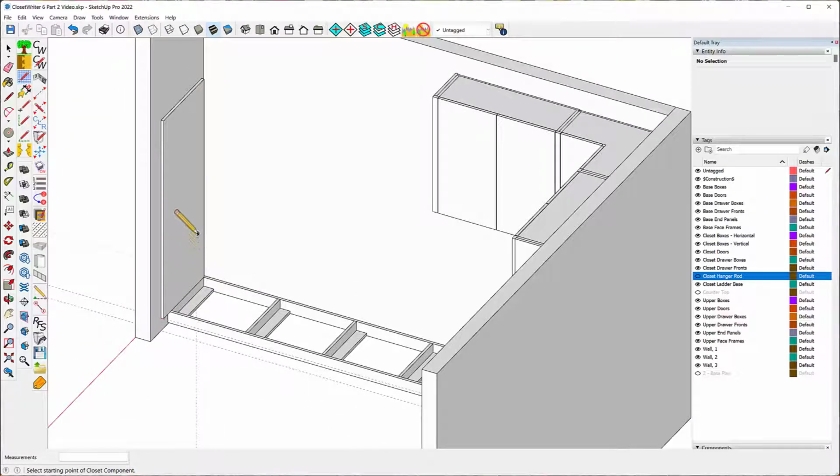So there's a number of ways that I can eliminate the shelf holes. One is to disable them on the Closet tab, and the other is to use the Shift key, which I can do on individual sides or partitions. So that's a way to control it individually. The other way is a way to control it globally. But now I want no shelf holes. And I'll explain this a little later, but it's also explained in that document I asked you to read.